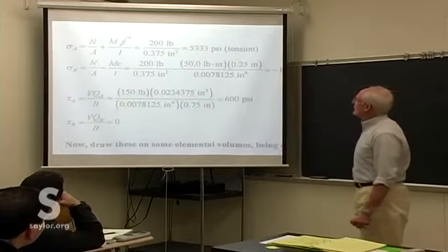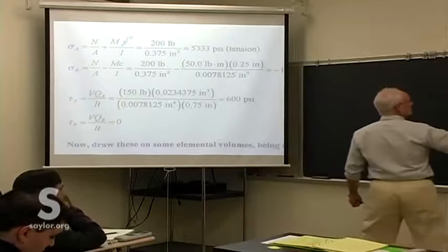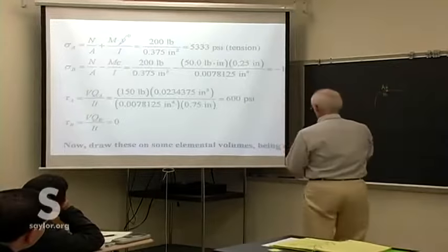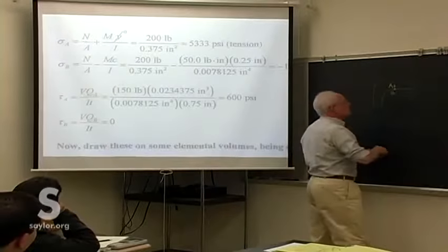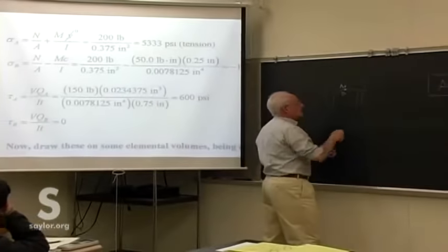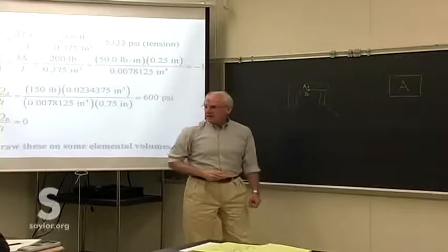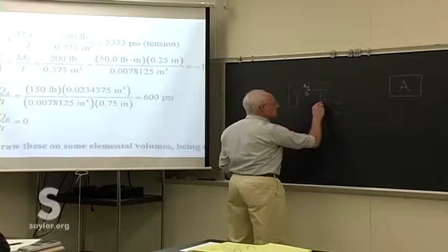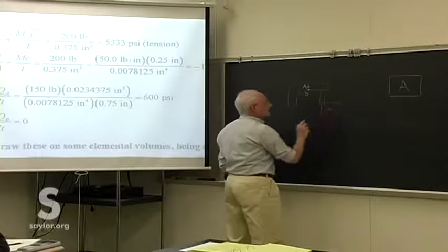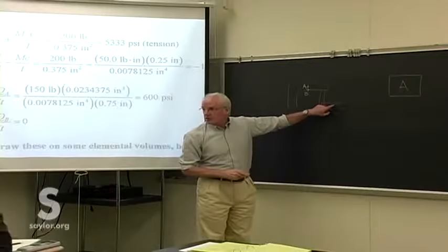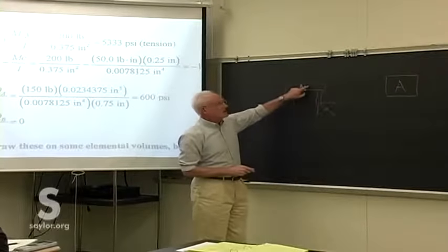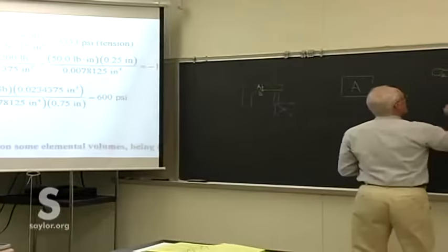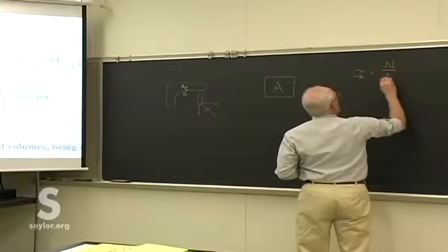At each one, there's a little bit different section properties, which is the main reason there's a change for those. But for example, the top one across, we're looking for the stress, the normal stress at point A. That was partly due to this normal force. There was a bracket there with a force being applied like that in the problem. That breaks into components like that, and it's this first component right here that's causing a normal force at point A. So that's what this N over A was.